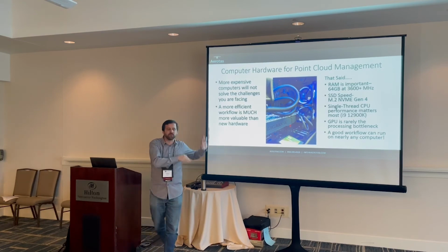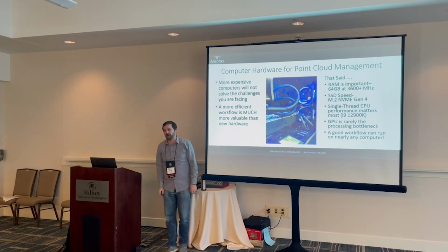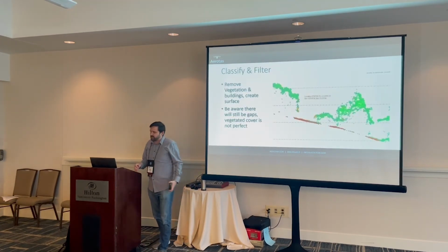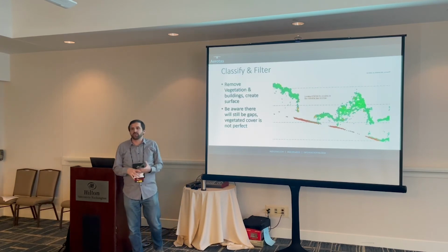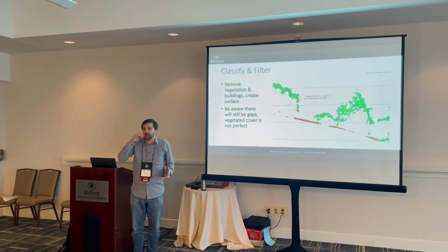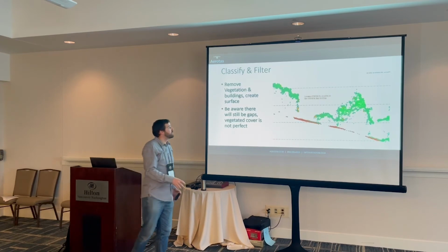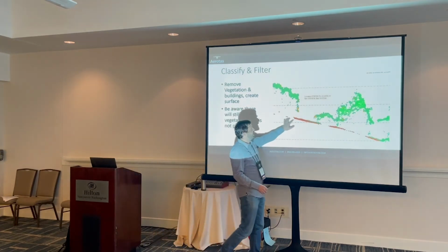Buying really high-end computers isn't really going to fix major LiDAR problems. All right, so let's talk a little bit more about classifying. Classifying ground is going to be almost always the most important thing. That's what we care about. Usually, when you're running LiDAR, it's because you're going to be running topo. So what you care about is the ground.